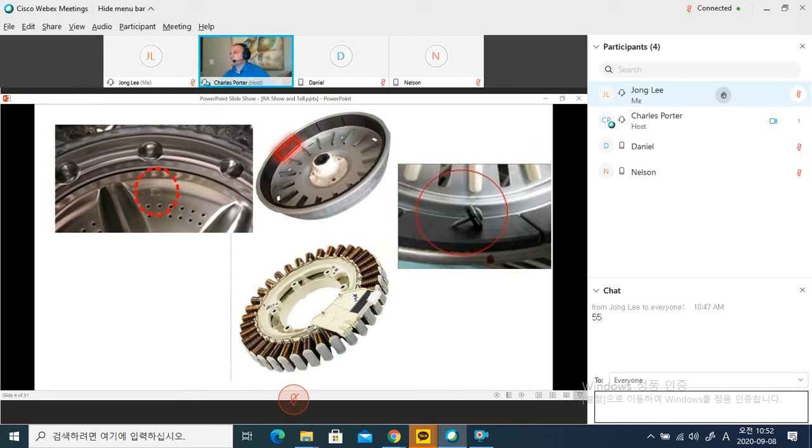So here you go. That middle top picture there is your rotor, and that middle bottom picture there is your stator. Your stator has all those coils going all the way around it, and that little connection there that's closest to you, sort of on the right, is your Hall sensor and your wire harness connector. So you've got your wire harness going to your stator, as well as the Hall sensor. That little black strip there is your Hall sensor, which is reading the movement of the motor.